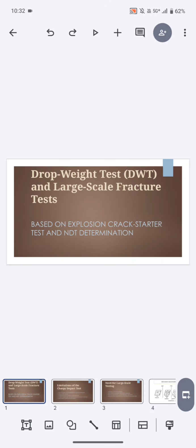Note this point. The FTE marks the highest temperature of fracture propagation by purely elastic stresses. At yet higher temperature, the extensive plasticity results in helmet type bulges. The temperature above which this fully ductile tearing occurs is the fracture transition plastic, FTP.